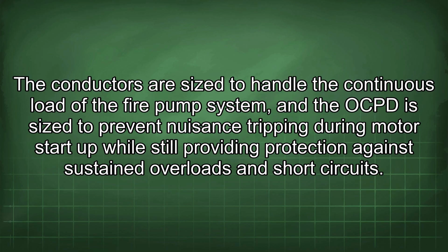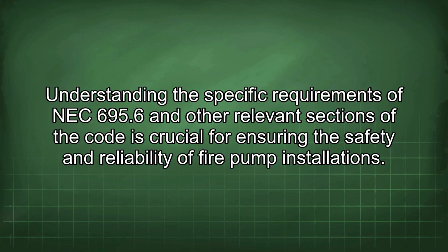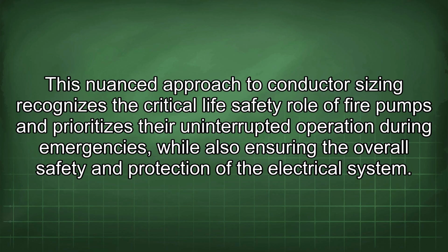The conductors are sized to handle the continuous load of the fire pump system, and the OCPD is sized to prevent nuisance tripping during motor startup while still providing protection against sustained overloads and short circuits. Understanding the specific requirements of NEC 695.6 and other relevant sections of the code is crucial for ensuring the safety and reliability of fire pump installations. This nuanced approach to conductor sizing recognizes the critical life safety role of fire pumps and prioritizes their uninterrupted operation during emergencies, while also ensuring the overall safety and protection of the electrical system.